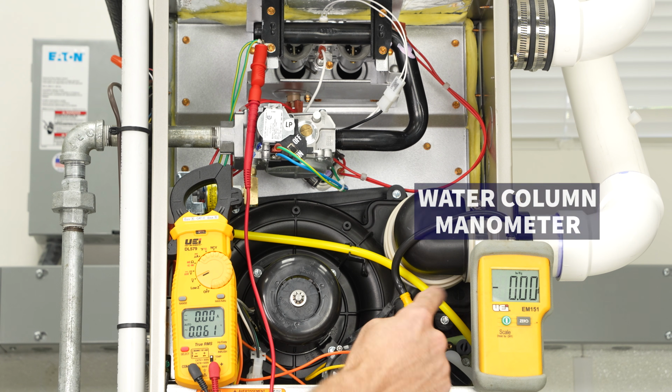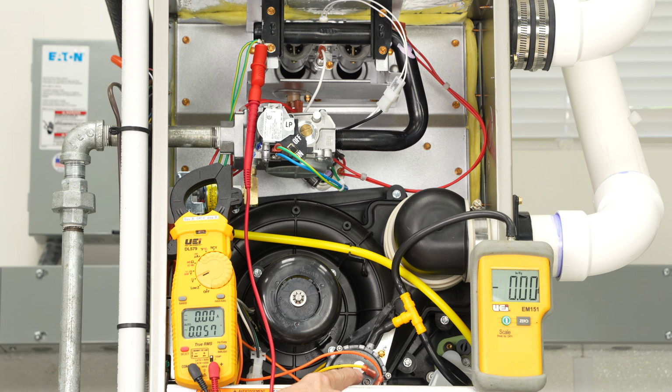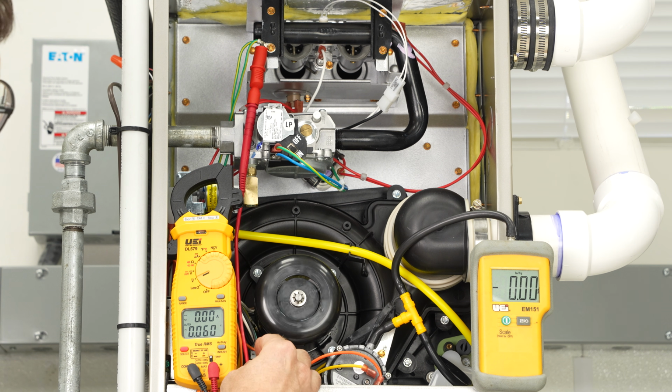So now we have our water column manometer teed in right here, and we're also going to take our voltage measurement on the pressure switch just to show that it is proving that the inducer motor is running.